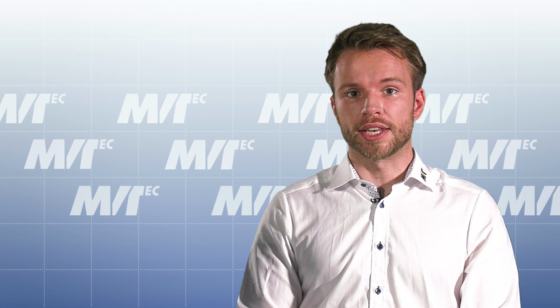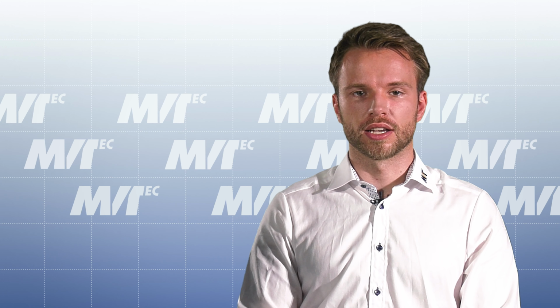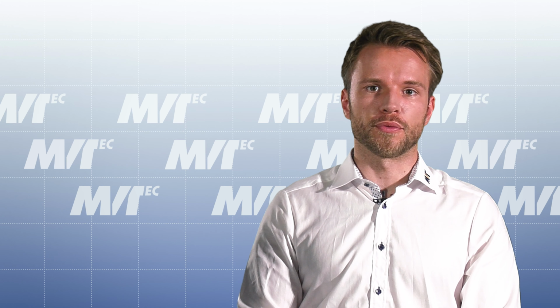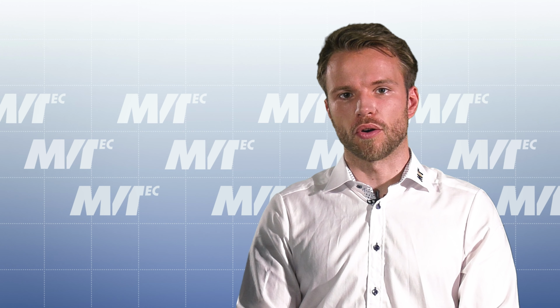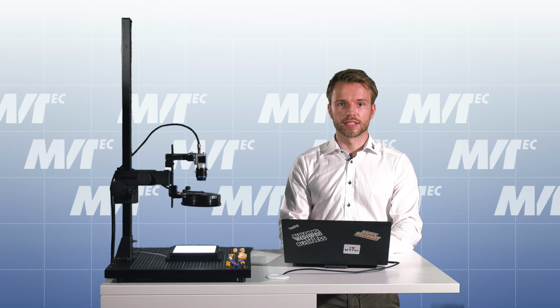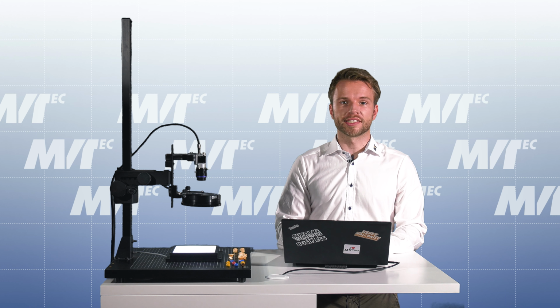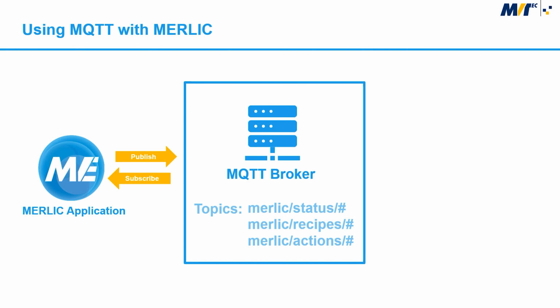Before we dive into the integration of a MERLIC vision application into an MQTT network, I'd like to give those who haven't worked with MQTT before a short introduction. In the center of every MQTT network is the MQTT Broker. Clients can connect to the broker, subscribe to different topics, and publish their own messages on a topic. In our scenario, one client is the MERLIC vision application.